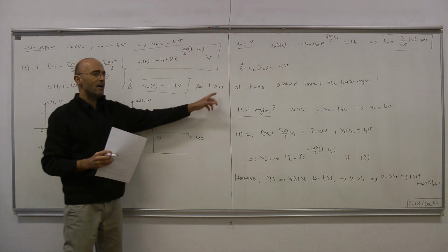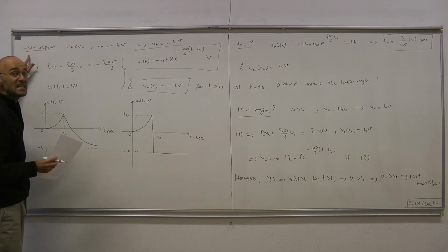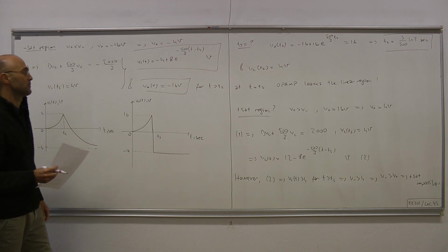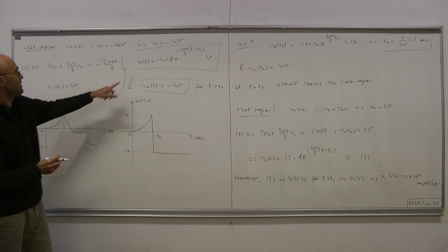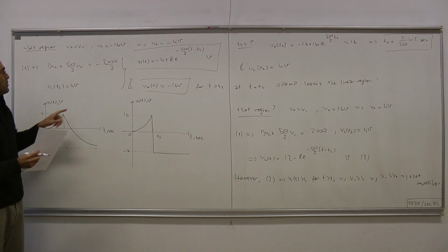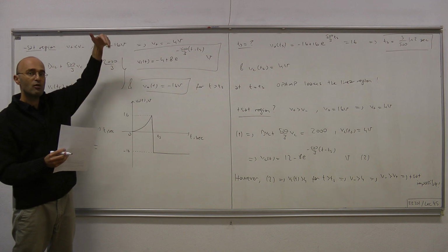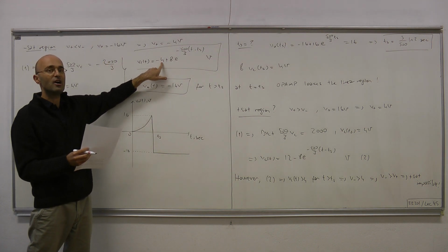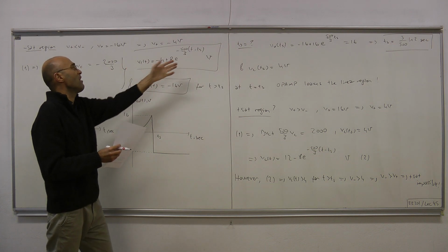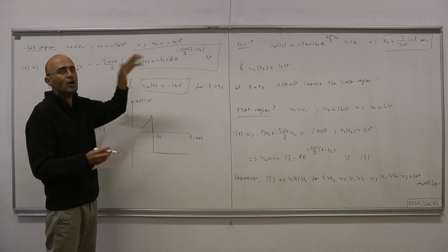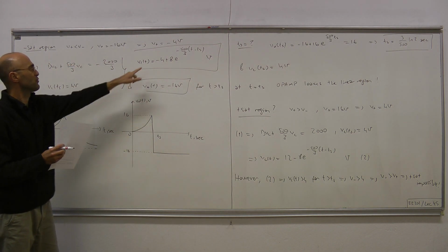Now let's check whether we have to do any further analysis, that is, whether the op-amp can leave the negative saturation region. So if you look at VC(t), it becomes closer and closer to minus 4. It approaches minus 4 from above. For any given time, it can be very, very close to minus 4, but it will always be just a slight bit larger than minus 4.